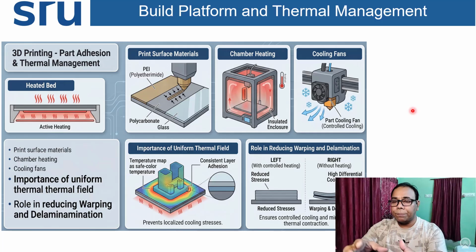Because of that, it is very important to understand and control the maximum temperature generated inside the build chamber. For that, sometimes we require cooling. There are different ways of cooling. You can cool down by placing some liquid nitrogen, keeping some quantity of the liquid or continuous feeding of liquid nitrogen inside the chamber.